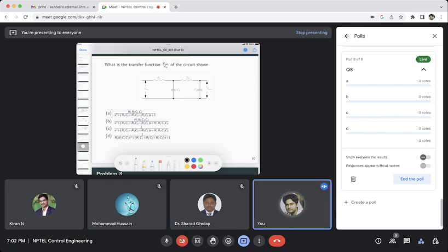If you remember, there is the loading effect, right? If some power is drawn, that means when you connect the circuits, the behavior will be different. You have two blocks here, this block and this block, these RC blocks. How they behave individually is different from how they behave when interconnected. There is some effect because current will be drawn from this. Let one current be I1 and this will be I2.